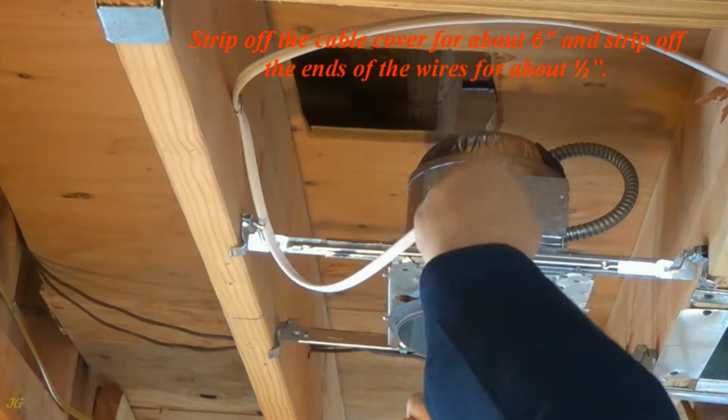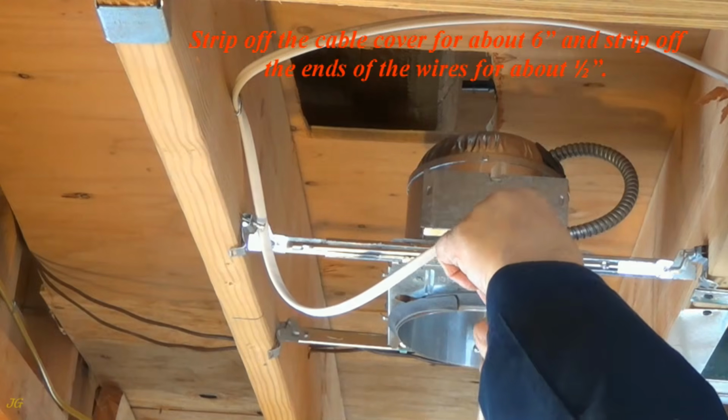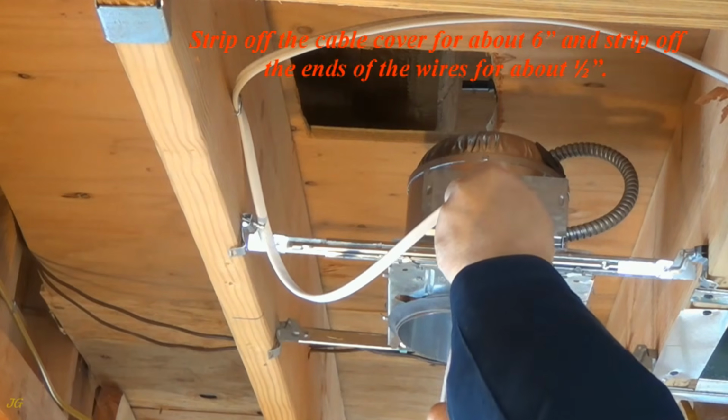Strip off the cable cover for about 6 inches and strip off the ends of the wires for about 1/2 inch.